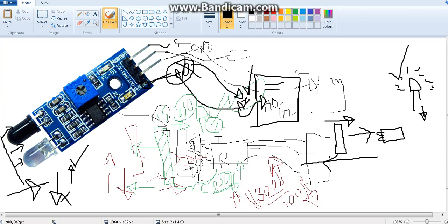When the object is most away, at the maximum point, I mean the 1000, let's come to that later, the brightness of the LED should be minimum, that means 0. So it is an analog indicator of the position of the object from the IR sensor pair. Earlier we had a digital indication: within the 15 centimeter range, or away from it. Now it's not the case. We are going to have an analog indication of how close or how far the object is.